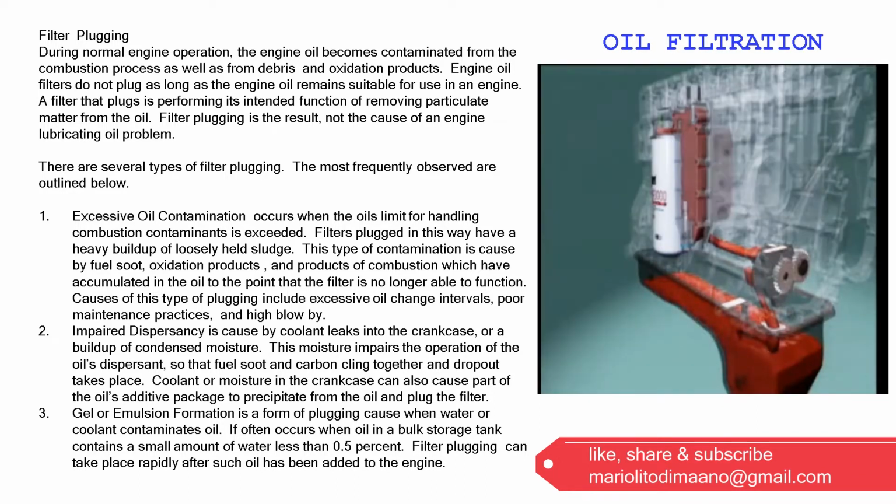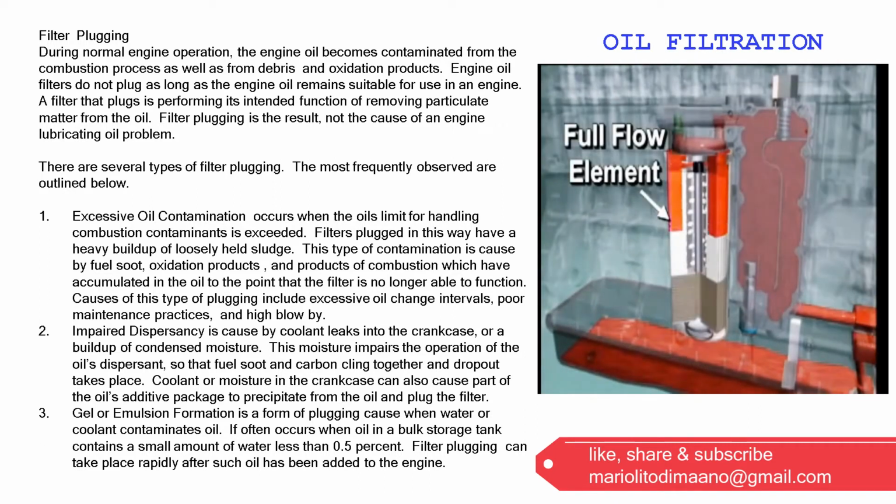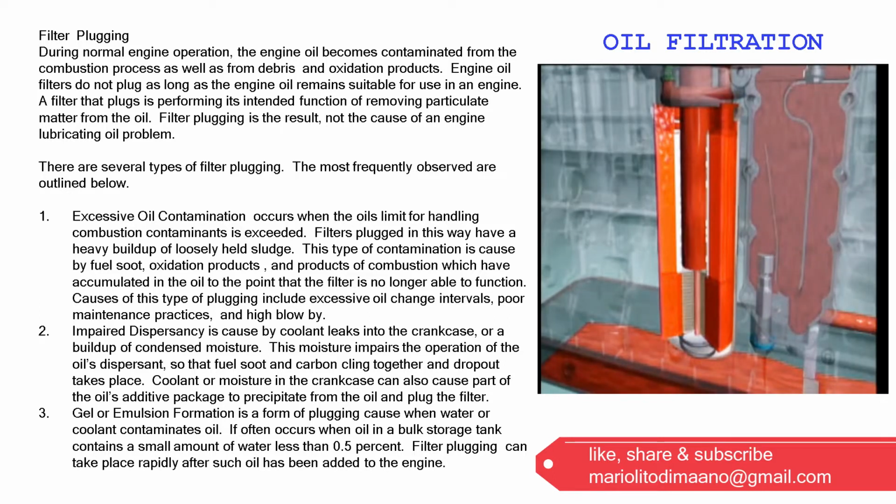3. Gel or emulsion formation is a form of plugging caused when water or coolant contaminates oil. It often occurs when oil in a bulk storage tank contains a small amount of water, less than 0.5%. Filter plugging can take place rapidly after such oil has been added to the engine.